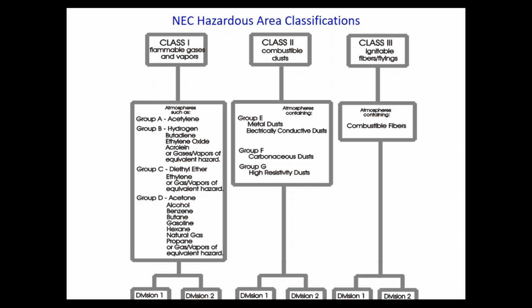Basically what that's telling you is that if I was to put a stoichiometric mixture of those chemicals in an enclosure with oxygen, and ignite it, I would get a certain pressure on a gauge that we'd have to design that equipment for, to make sure that our equipment doesn't bend, stress, crack, or blow up under that pressure.